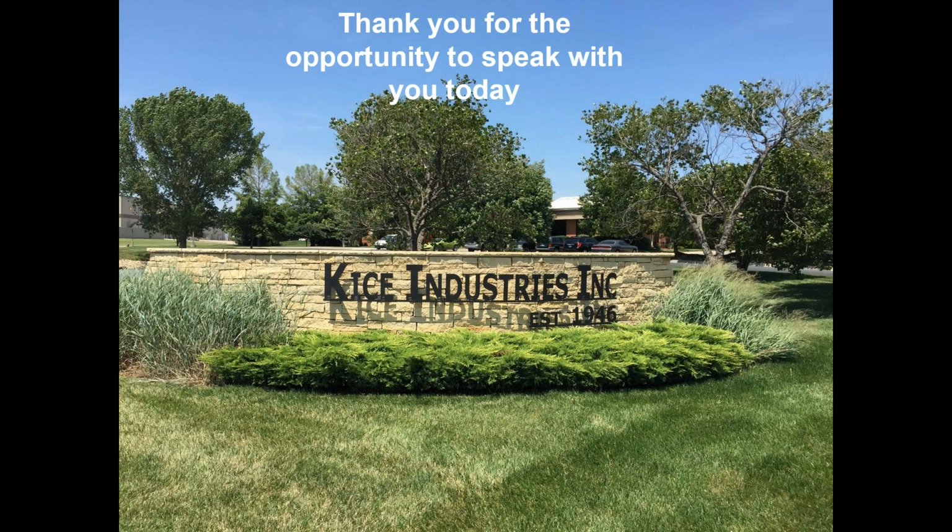Okay, our next question. Can you use your compressed air system on a filter that requires a separate blower? No. The short answer is no. The reason is the intention of that style of filter, what we call our high volume cleaning mechanism. A typical air compressor isn't going to be able to provide the volume of air in any good amount of time to be able to clean those filter bags. Now, you'll be able to create enough pressure, but we're not going to be able to fill that larger air tank up enough in a good amount of time to get an effective cleaning.